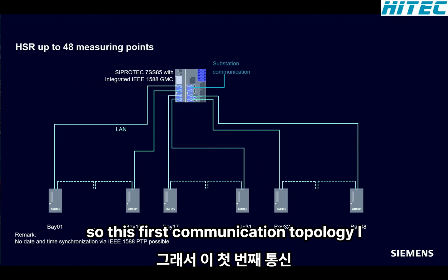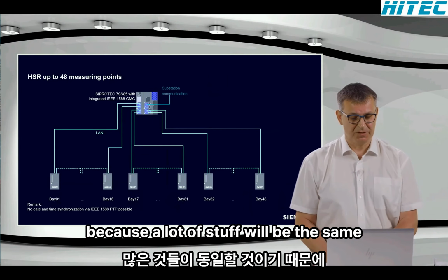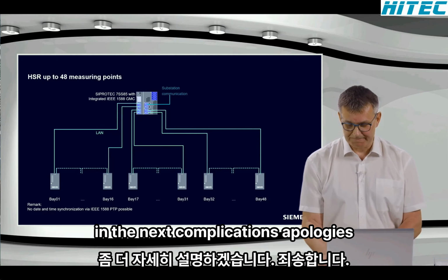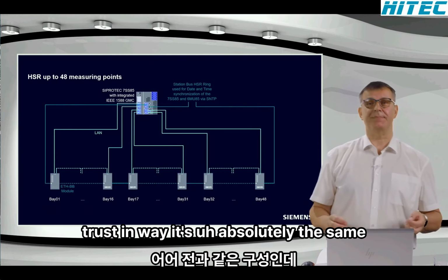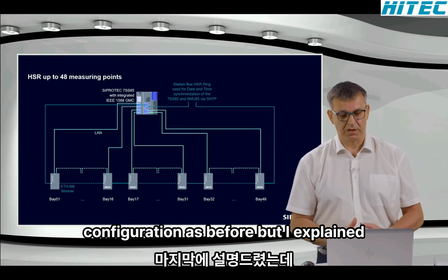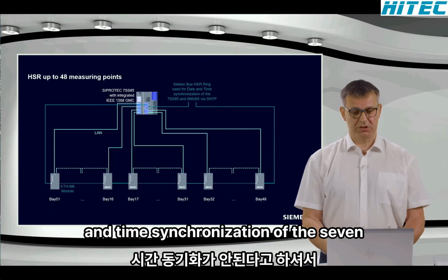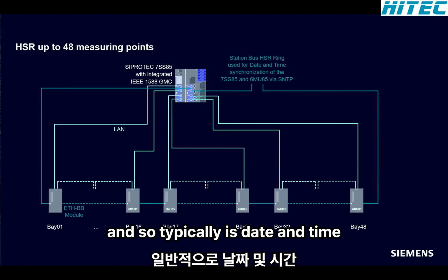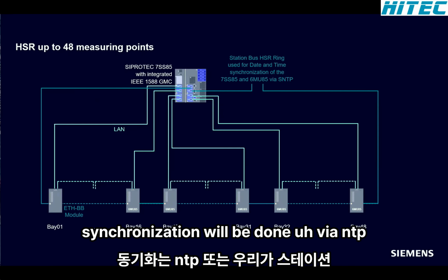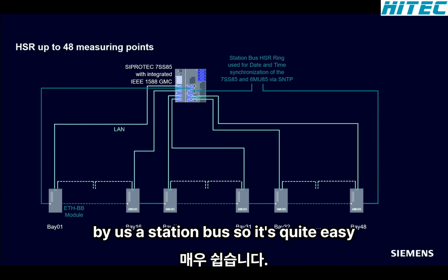So this first communication topology I explained a little bit more in detail, because a lot of stuff will be the same in the next communication topologies. It's absolutely the same configuration as before, but I explained to you at the end that no date and time synchronization of the 7SS85 and the bay units is possible. So typically this date and time synchronization will be done via NTP or SNTP, which will be connected via the station bus. So it's quite easy.